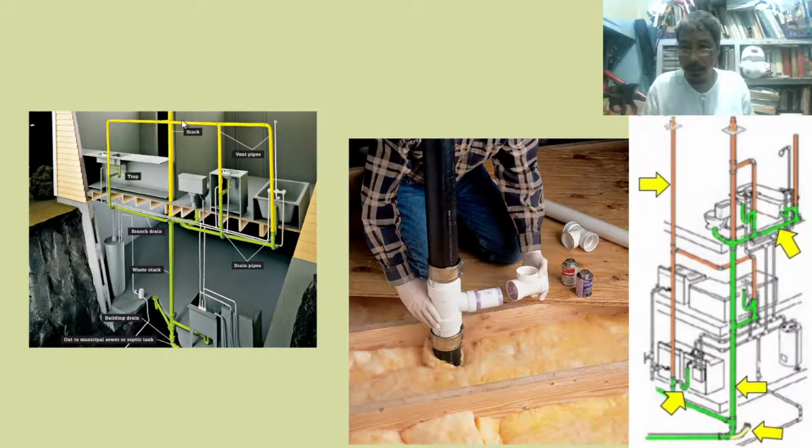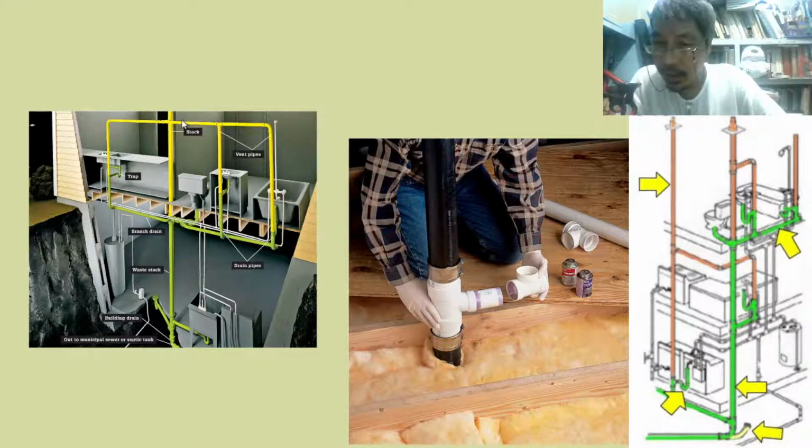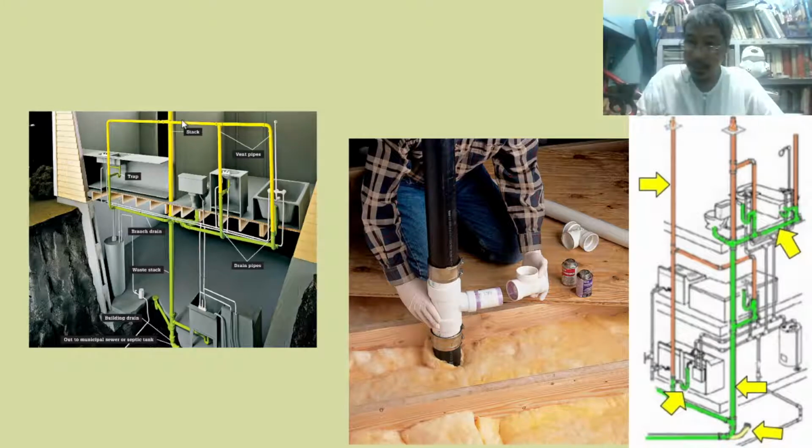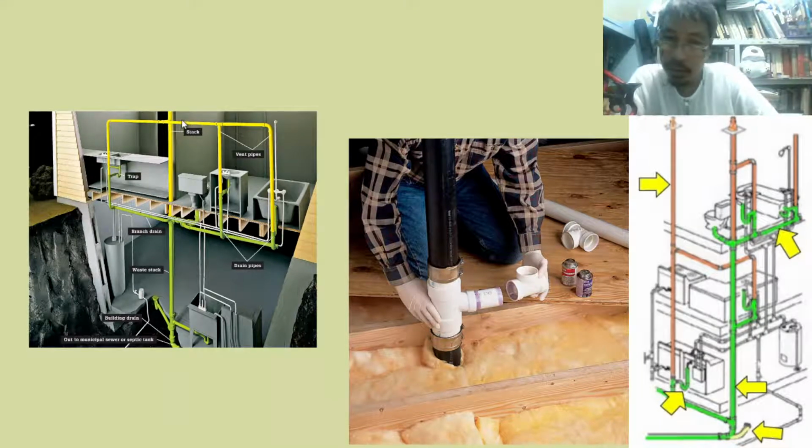If air is introduced into the different paths inside the system, it is better in order to avoid clogging. Sometimes the water would flow in reverse direction because of clogging. That's why we need vents, in order to introduce air from the atmosphere inside the system to prevent clogging.